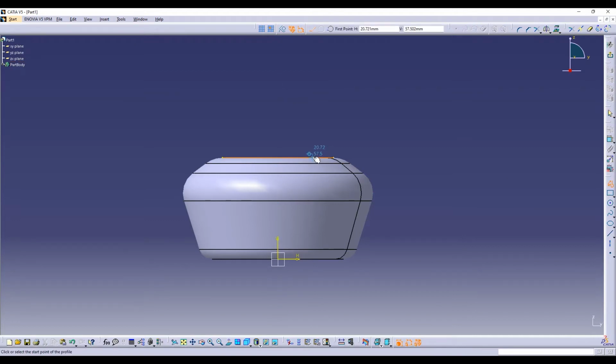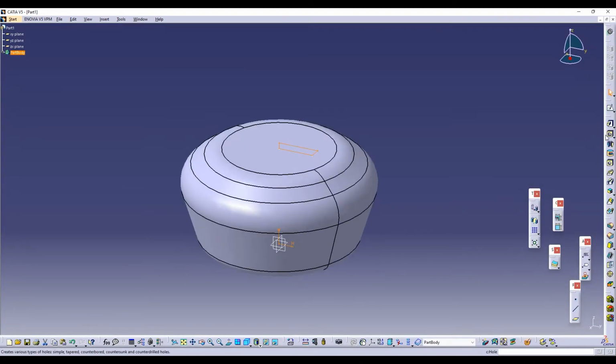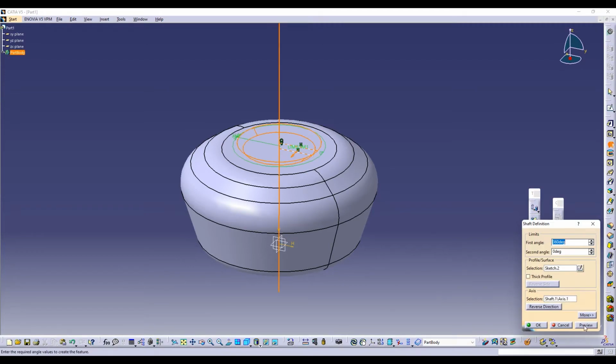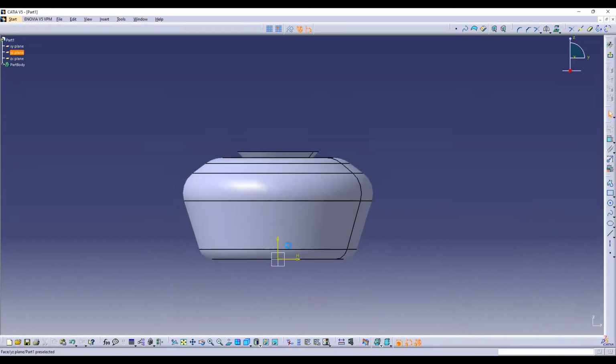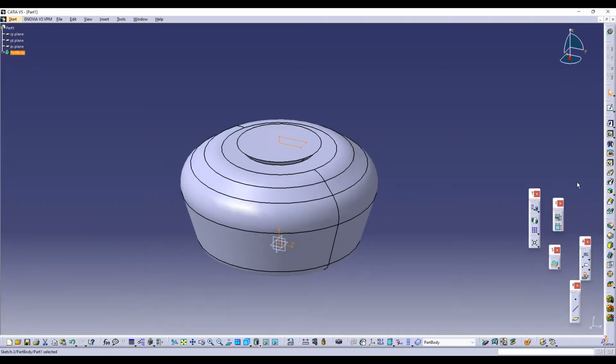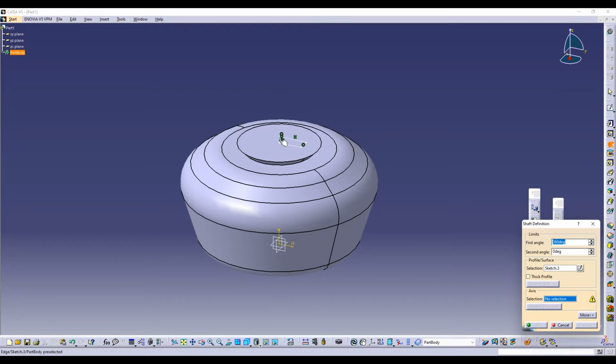Let's draw the camera angle. Then we'll trim all this. Revolve it. Done. Again, one base stand we'll make here. The new base stand will be slightly lower than the previous one. Let's trim this again and then exit. Let's revolve once again. It's done.